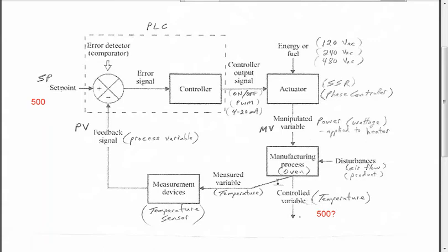that. The feedback loop is this path here. You're simply going to monitor the process variable, or here I guess the author lists it as the controlled variable. You're going to monitor it somehow, and you're going to use some measurement devices to do that. It's a little confusing, I think, in the diagram. He puts these two almost like they're different things, but maybe if you follow the line back to here, they're the same thing, really.